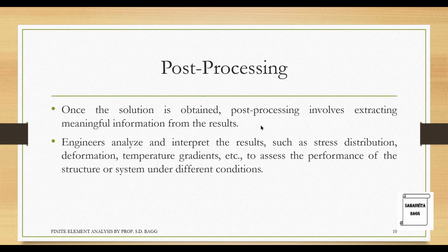Next step is the post processing. This is the last step actually. Once the solution is obtained, post processing involves extracting meaningful information from the result. Once you obtain the results of temperature, displacement, stress, strain, whatever you obtain, it is important to understand the meaning of the colored results obtained. Also, you need to interpret the value that you have got.